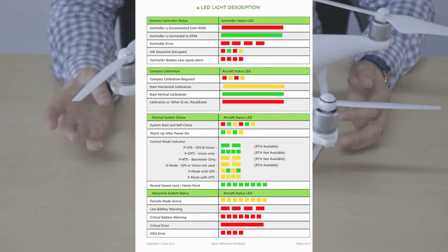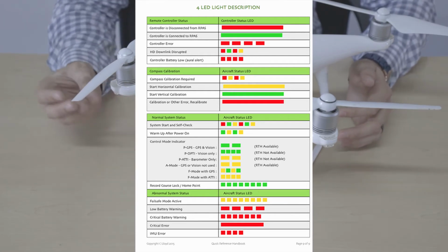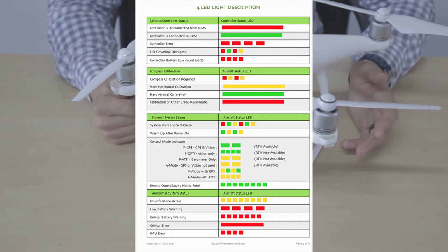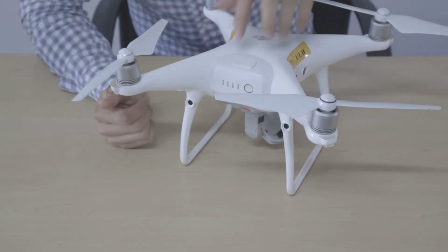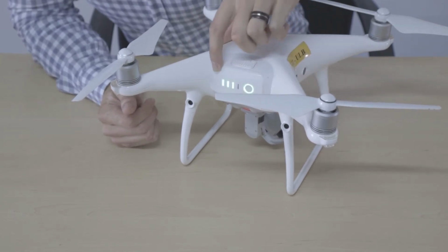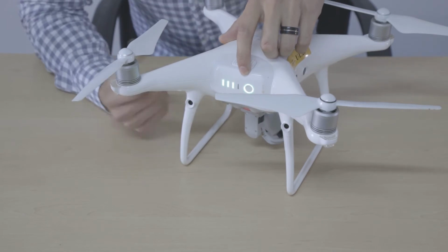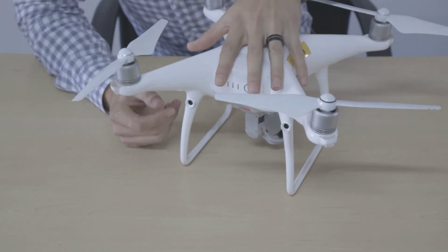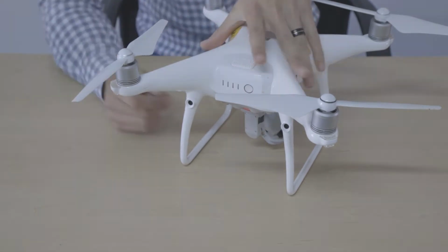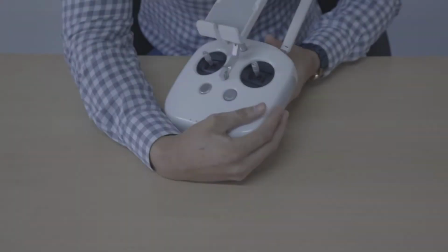Next is red LEDs, or red flashing LEDs at the back, and this means land the aircraft immediately. This can also mean that you have reached low battery, so bring in the drone for landing. Other components might be totally switched off and might pose risks for the flight as well, so this will also mean bringing in the drone immediately.